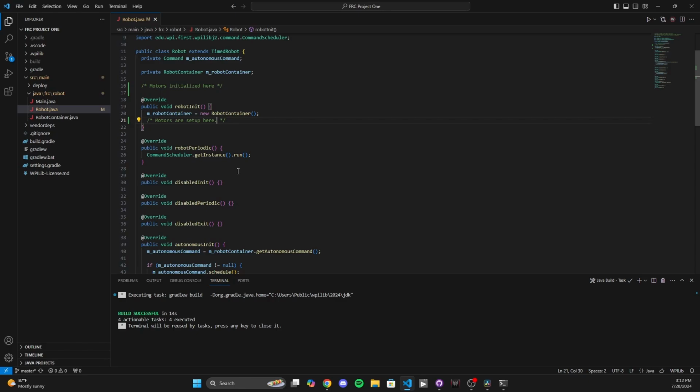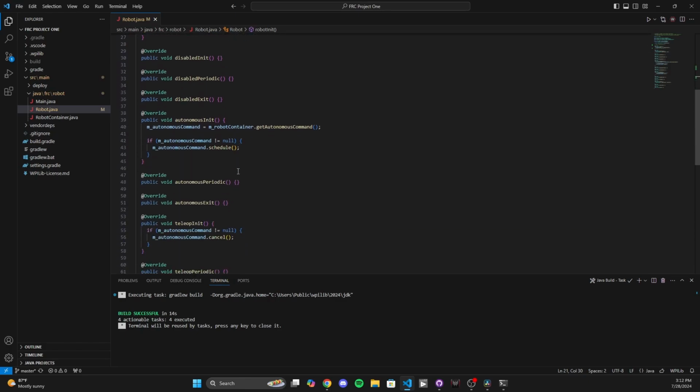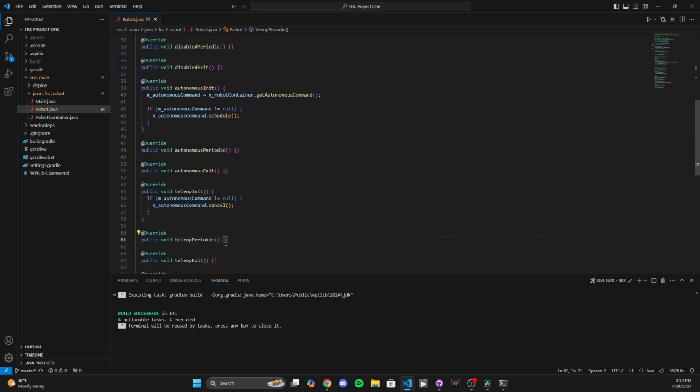The most important one we're going to go to is teleopPeriodic, because of what happens in teleop. We're going to focus on autonomous at a later part in this course. The big focus for now is just going to be teleop. In teleopPeriodic, this is where motors do stuff. So that's where I'm going to turn on my motor and do something. That's really the big idea about Robot.java: they have all these different kinds of methods that get used.